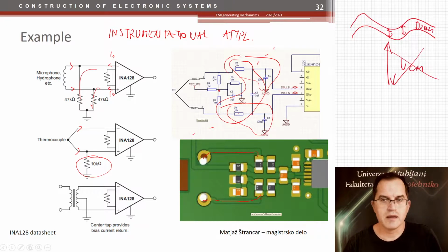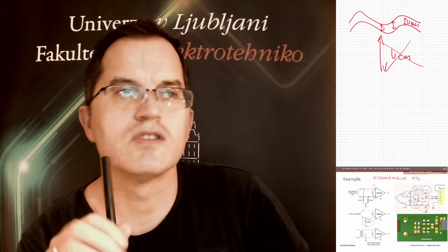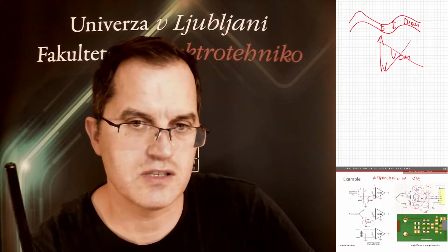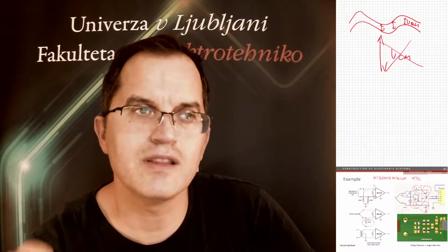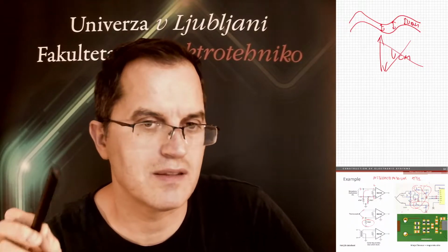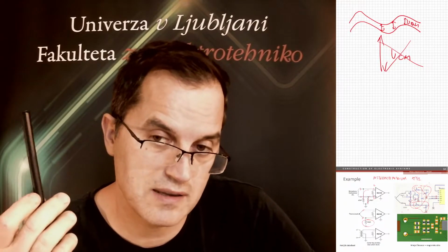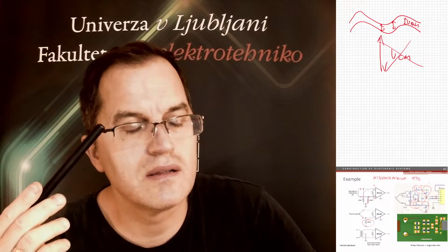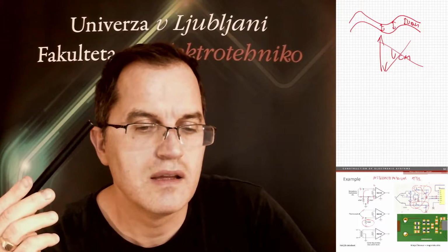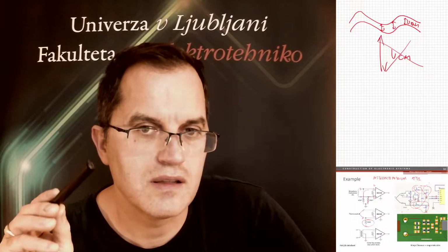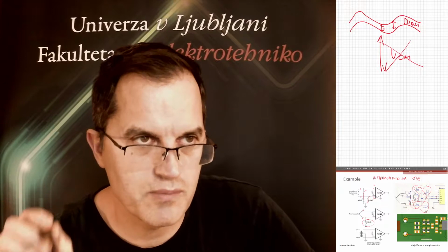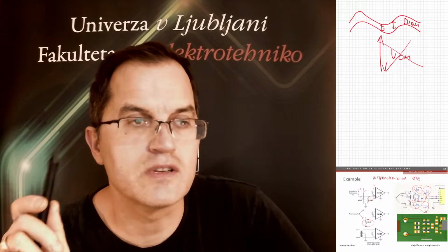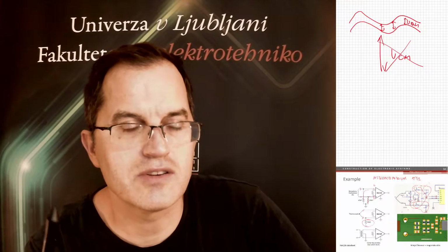So to sum it up at this stage, I must say that designing your designs fully differentially and symmetrically at the points where your problems are likely, where you have a very high chance of getting noise into the circuit, such as input amplifiers, which are very sensitive, as I said before, you have to take care that your design is totally symmetrical in any way.